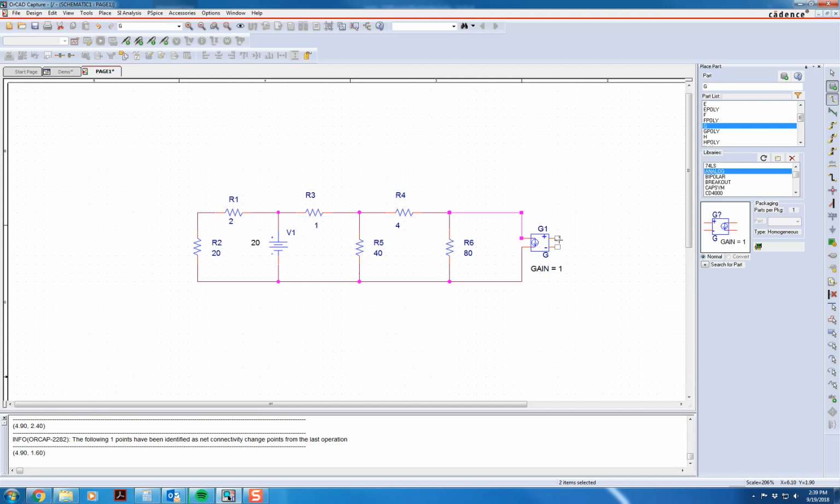Now I'm going to do the negative side of the voltage. This is where you have to be a little bit careful when you're reading these diagrams. I'm just left clicking on the negative side. So now I'm going to move R4, move this back up. Now one thing I want to point out here is notice that of course these wires are crossing right here, but there is no actual connection being made. So the diagram, because we have to just set up the circuit for the simulation.